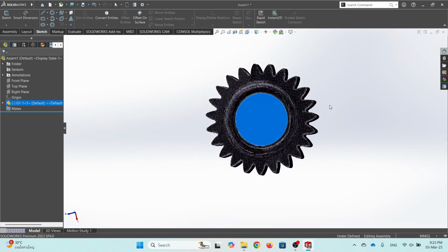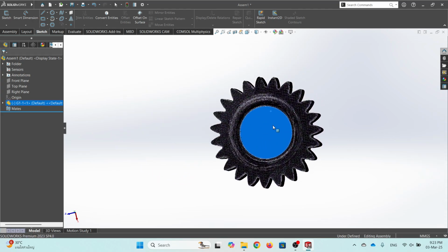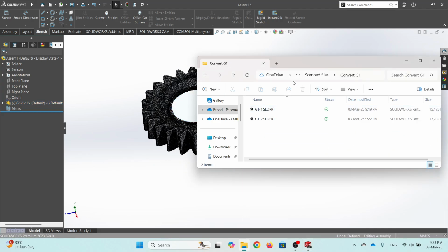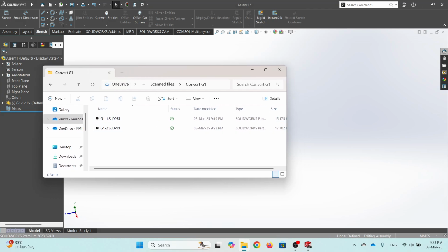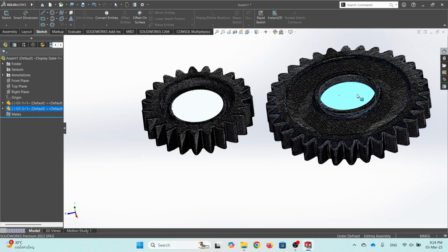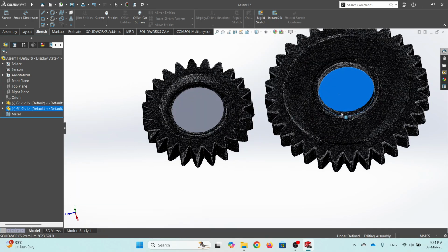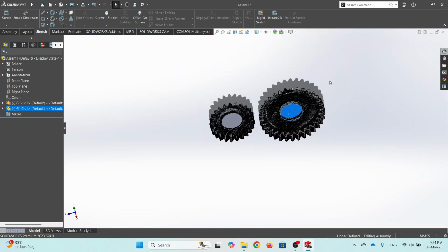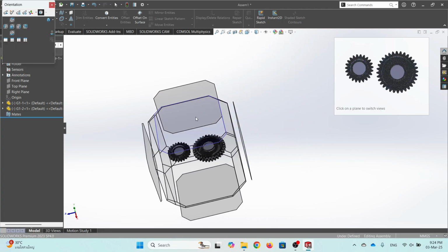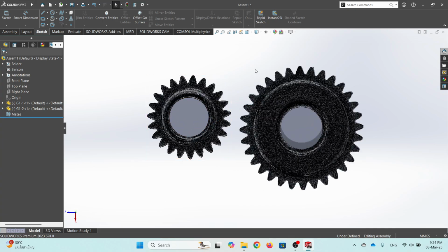Okay, in this case you have to click on this solid body to move it. Okay, and after that you just import the second part, which you can do by going to your photos that you saved and directly dragging them into the software. So then after that you just click on this face also, and when you want to align them together, you click the spacebar key, and then you look at it from the top view, right?